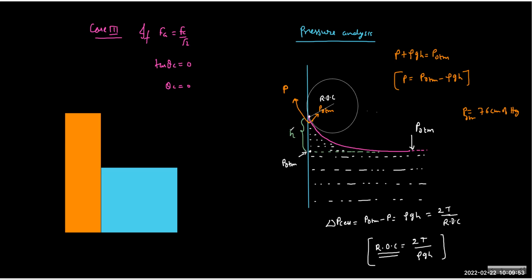And the flat surface will have H equal to 0. So this is completely justifying the scenario, because as you vary the H, we have different radius of curvature. And if you come almost near the flat surface, then the curvature becomes infinite and it will become basically a flat surface. So that is what we have proved here using this concept of excess pressure.